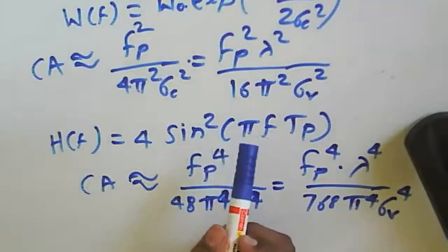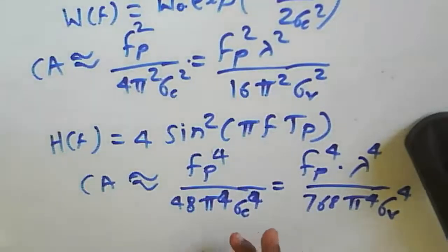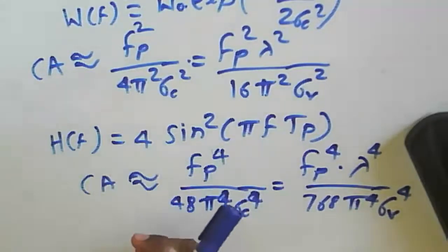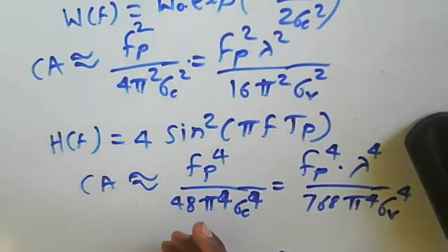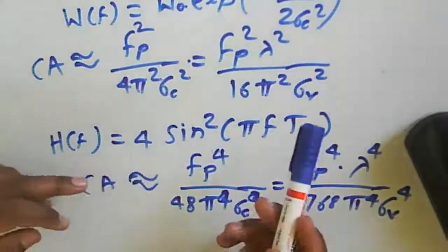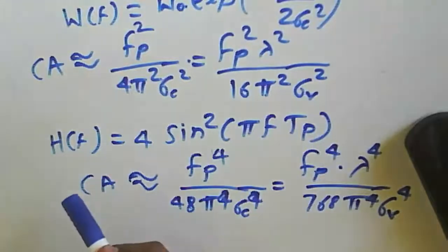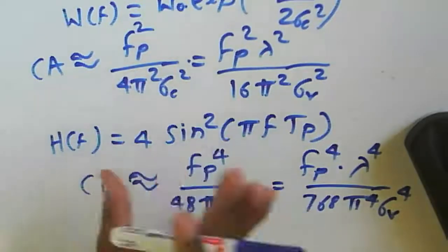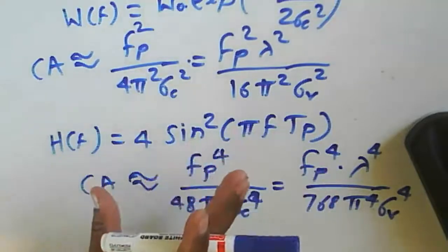If we use the nth power of a single delay line canceller instead of a second one, that is, n delay line cancellers in cascade, then there will be an nth power, and the clutter attenuation will occur in terms of n.